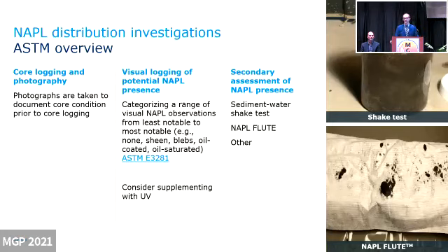As Mike had pointed out, it is often pretty hard to see NAPL in sediment because sediments are typically dark and the NAPLs are also dark. And so there are some recommendations in the standard to consider using UV light to help enhance that, and I'll be discussing that more in a moment.